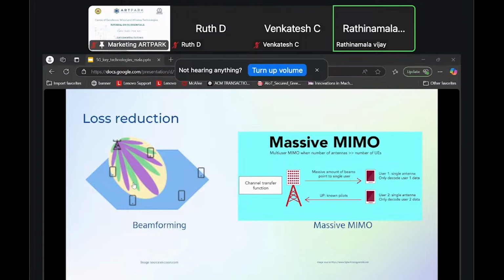There are also several types of beamforming. Dual polarization is another type, where the electromagnetic waves that are transmitted are polarized both vertically and horizontally. This means the antenna system can transmit and receive signals with two different orientations, which improves the system's ability to handle interference, multipath, and spectral efficiency.